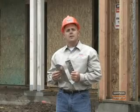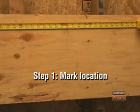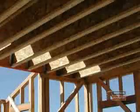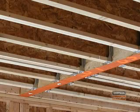The first few steps in the installation process are the same for many top flange and face mount hangers. The first step is to measure and mark the intended location of the joist on the header so that you know where to install the hanger. The second step is to position the hanger. When joist hangers are correctly positioned, a series of joists sit at a consistent height.